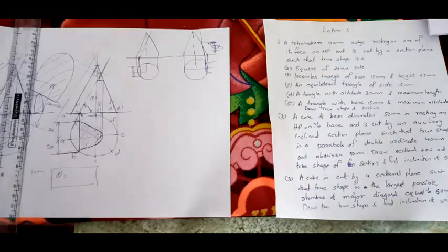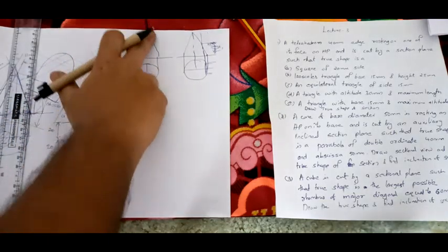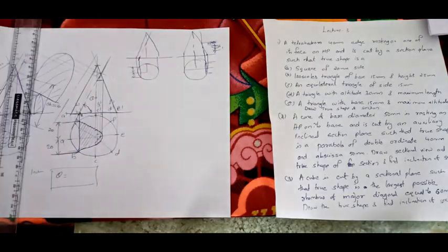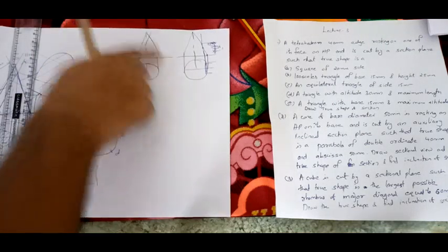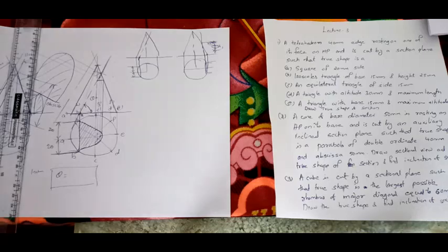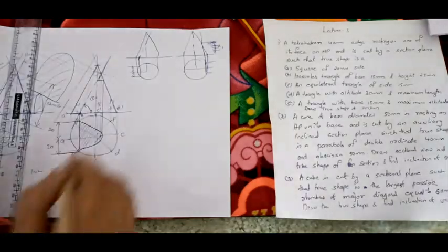So it is similar to the parabola. For a right hyperbola the section is perpendicular. A parabola is parallel to what? Parallel to the generator, either of the two true generators. There are only two true generators, each true and visible. Parallel to them, you will get the parabola. Right. Before going to the next question, I will tell you how to draw.